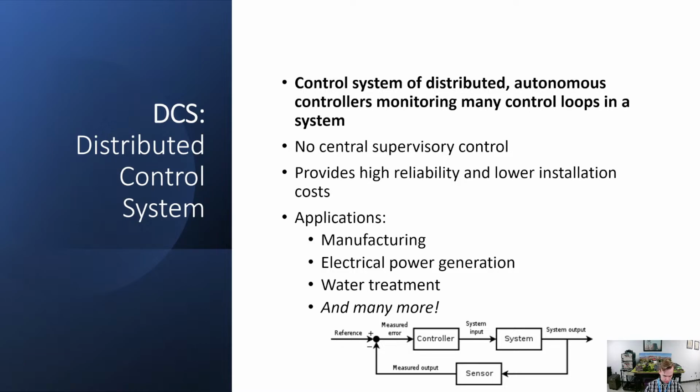So these control loops contain some type of process sensor, say like a temperature sensor, a controller function that takes in data from that process sensor and interprets it, and then what's called a final control element. And that is just a process that automatically tries to take in the data from the sensor and the controller function, measures the data coming from them, and tries to adjust the environment that control loop is placed in down to a desired set point. That would be set by the operator. So just a control loop monitoring the environment and trying to adjust the environment however it can to try to get to a steady predetermined state.